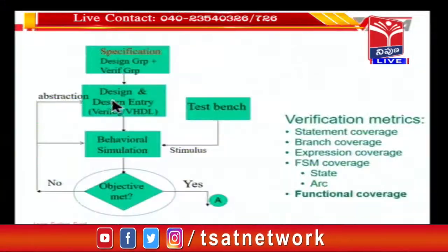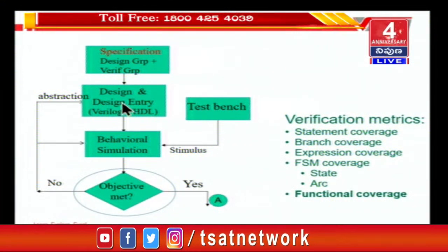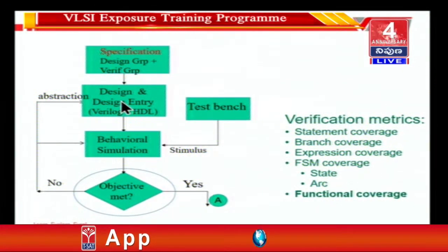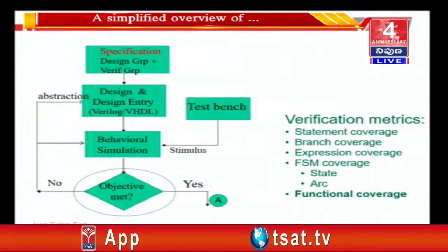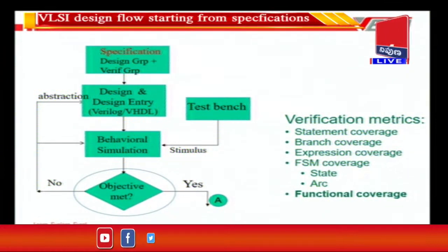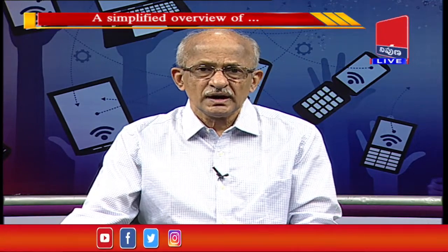So that's how it is done these days, at a high level of abstraction, and the underlying logic is not assumed to be in any form or technology. For example, if you want to write the functionality of an adder, the main execution statement of the Verilog code is y is equal to a plus b. That's all. A could be an 8-bit quantity, B can be an 8-bit quantity, and Y can be a 9-bit quantity. As you all know, if you add two 8-bit quantities, you will get a 9-bit quantity.